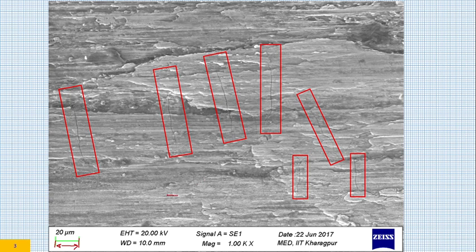This particular work material is titanium Ti64. That means titanium, aluminium, vanadium: titanium, 6% aluminium and 4% vanadium, Ti6Al4V. This has been ground by a silicon carbide grinding wheel at 30 meters per second, 2 meters per minute, and at 10 micron, with ample supply of coolant.